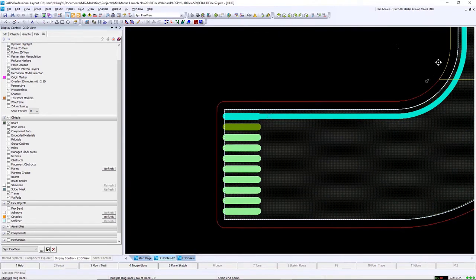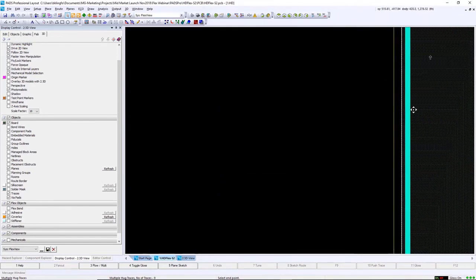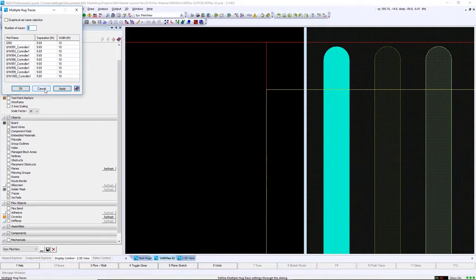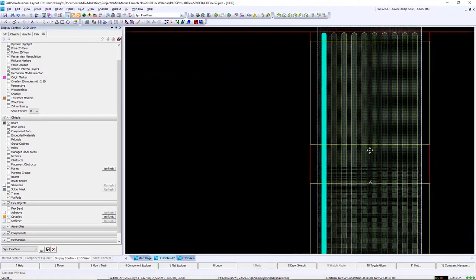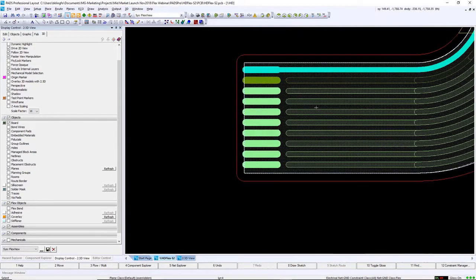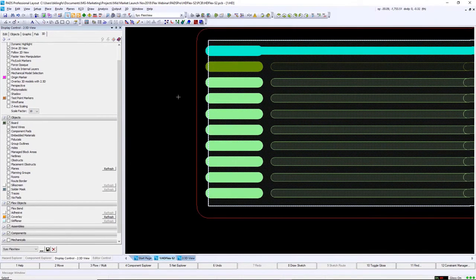After selecting all the pins, select where you'd like the new trace to start on the template trace or object. Then select the termination point. Click on the side of the object you want the new traces to be created. All 9 traces will now appear. To finish off the traces at the edge fingers, draw one new segment and copy-paste to the remaining.